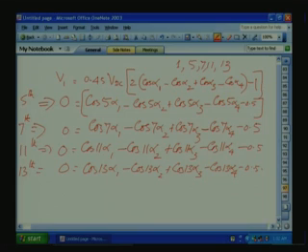So, if you see here, we have 5 equations, and we have 4 unknowns to be found out. Based on these 5 equations, we have to find out alpha 1, alpha 2, alpha 3, alpha 4, such that V1 is our required value and these harmonics are 0. If the output frequency is fixed, then the required RMS V1 we can put in and solve this.